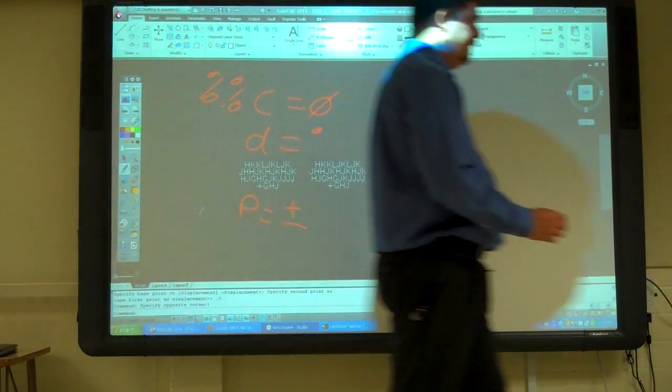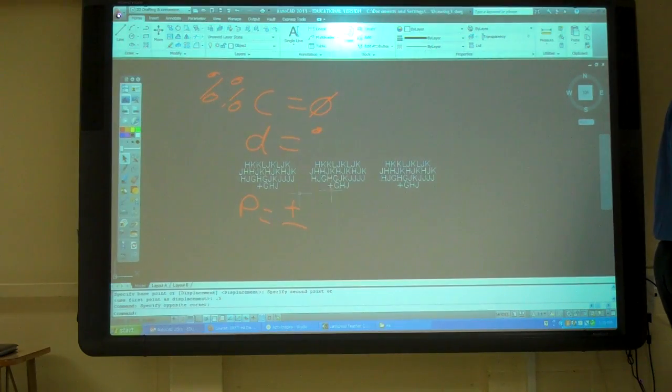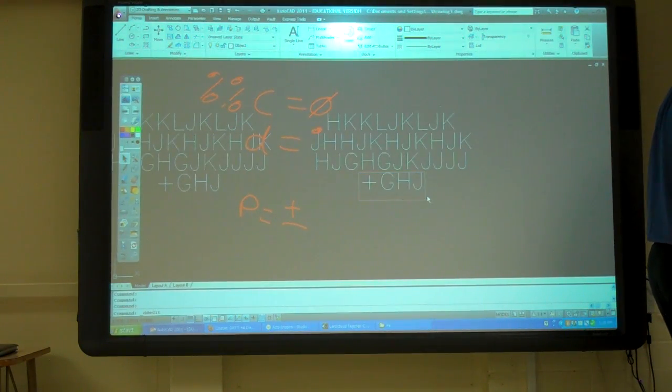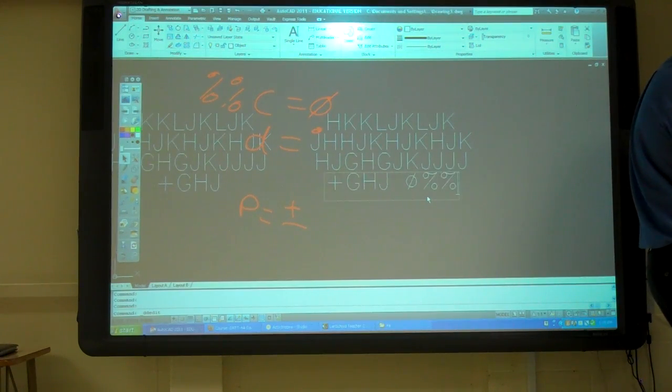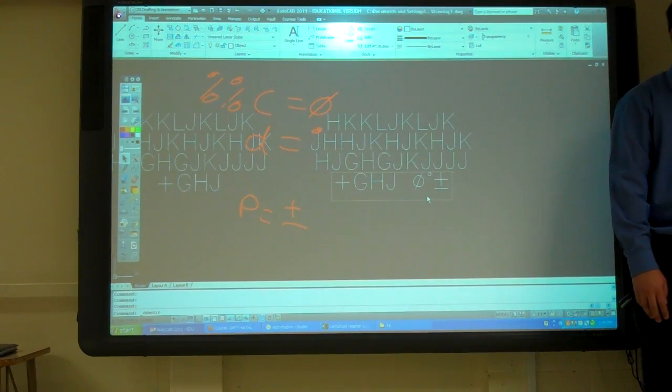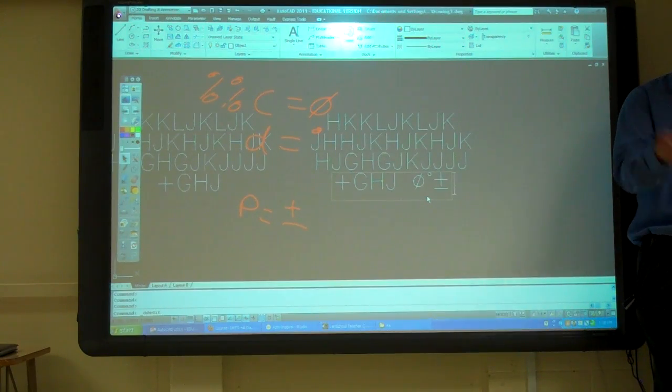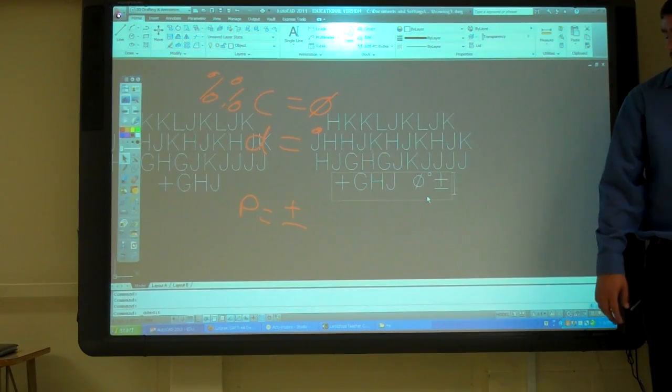So if I go and edit one of these texts, I say percent C, diameter symbol. Percent D, degrees, percent P, plus or minus. Okay? Those are kind of real common ones, symbols you use a lot. So that's how you get them.